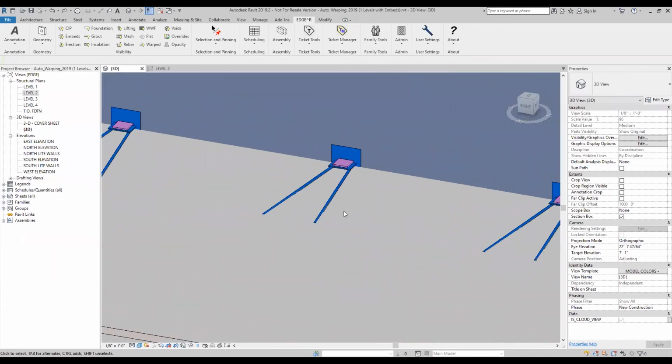For example, let's consider a spandrel to double T connection family. This connection family is composed of 3 nested families: a double T plate, spandrel plate, and erection material. Since the double T is cast in the flat state and is warped during erection, the original double T plate and erection material should remain in the flat state and should not have an offset value control their placement. Instead, direct shapes should be created to represent their location in the warp state.